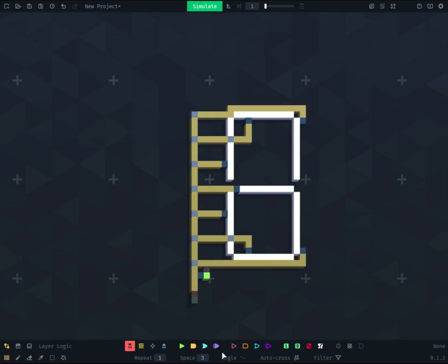And how does it work is that, well, to put it simply, we're gonna enable this latch, so this wire is gonna be on, and since this wire is gonna be on, this latch is gonna receive a positive input, and since it's gonna receive a positive input, it's gonna output a positive input. So it's gonna output something positive here, and we're gonna do that to every segment we want to light up.